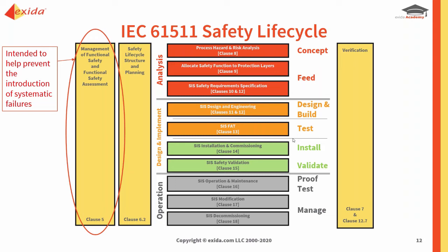And of course, the third one has to be done before we start up. So in the old 2003 standard, the FSA 3 was the only mandatory one. Now in the 2016, the language is such that if 3 is the first one you do, then you have to make sure you cover 1 and 2. So it really means that you should do 1 and 2, because again, the further down the life cycle you go, the more expensive it becomes to fix problems if you find them.